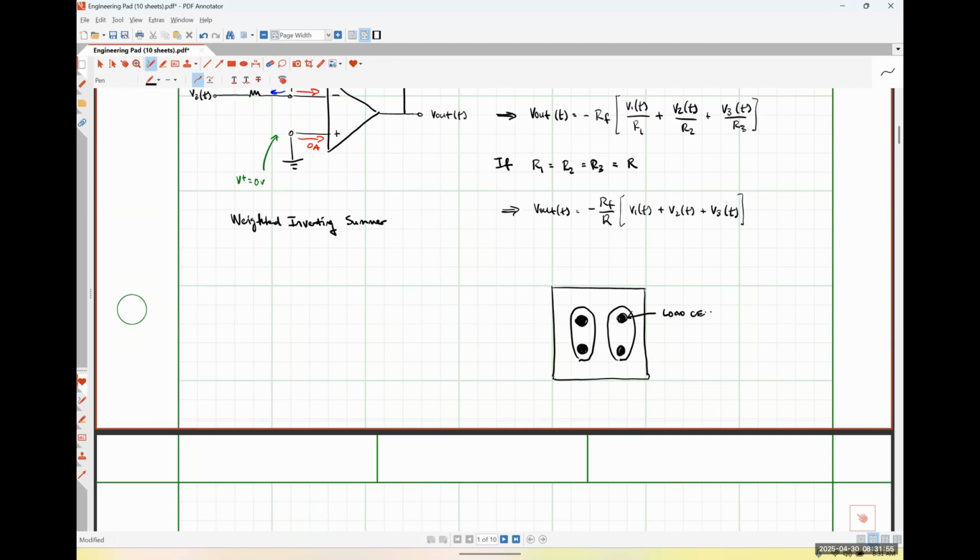So these are all just load cells, okay? And what these load cells do is they convert the strain of me stepping on them into an electrical signal. It could be a simple thin film load cell. It might be a nickel strain gauge, depending on what size of load you're measuring. But essentially, the change in the pressure that I'm applying to this load cell is generating some type of output voltage. And in this case, I have 4 output voltages, which I need to combine together to compute the overall weight on this digital scale.